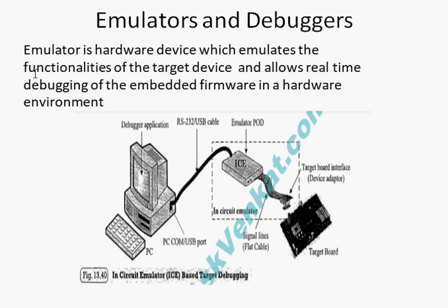So basically what the emulator does is it tries to copy what the target does. You give some commands. The commands will go to the target machine using this emulator, and it will process the data accordingly, and later that processed data you can observe in your host machine. So whatever the target processes, you can visualize the information in your host machine with the help of this emulator. It mimics the target, and you can get it in your host interface.